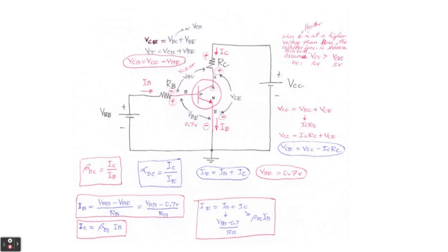Now moving on, let's go back again to our formulas. We have discussed the formula for VCB or VBC, and then the beta and the alpha, and the IE and the VBE. And the VCE also, if you want to calculate, is VCC minus the VRC, but VRC by Ohm's law is ICRC. Now the IB, as I have said, is equal to VBB minus VBE over RB, and the VBE is 0.7 volts for our silicon transistor. Just in case it's mentioned in a problem that it is germanium, then you have to use 0.3 volts. So if you want to calculate the IC, you may use beta multiplied by IB. And again, the IE is equal to IB plus IC.